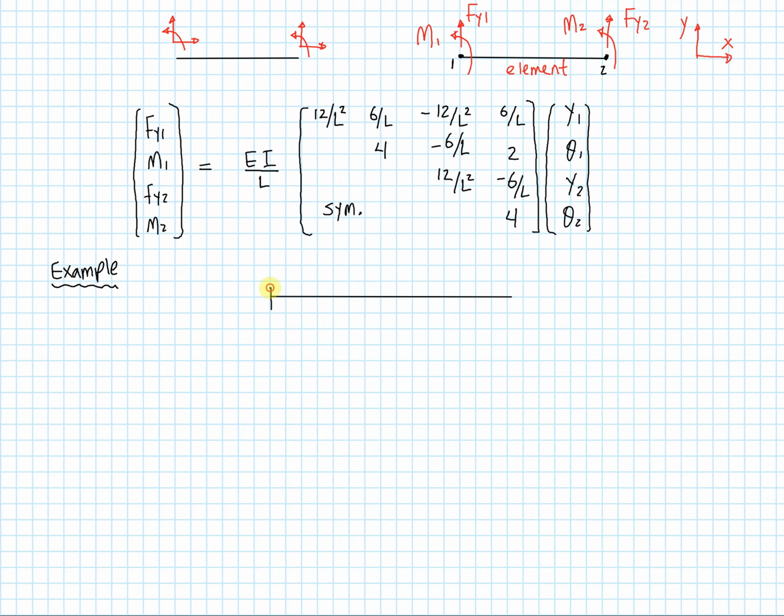This is going to be my fixed connection on the left-hand side, and I'm going to denote this by A. I'll have a roller element here. With rollers, I typically draw them as a ball. You could also draw them in all sorts of ways. We have node B, so that's going to be 1 degree of freedom here. And I'll have this free end here that has no support reactions, so it's almost like a cantilever. It's up in the air.